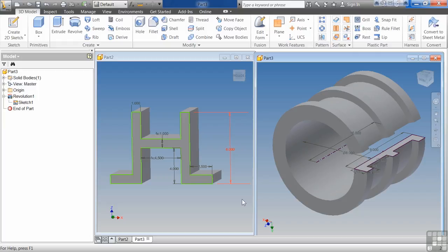But for the base feature, you have to have an unconsumed sketch, and likewise, sketches can be used for a secondary feature, but once again, it has to have an unconsumed sketch. When we get to talking about secondary sketches, we'll talk about sharing sketches and how to reuse sketch data. The result of the sketched feature can add or remove mass from the 3D geometry.